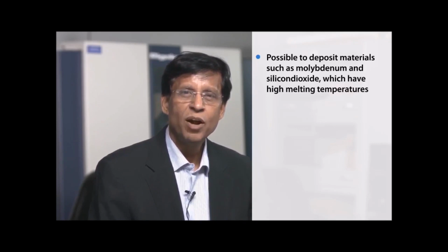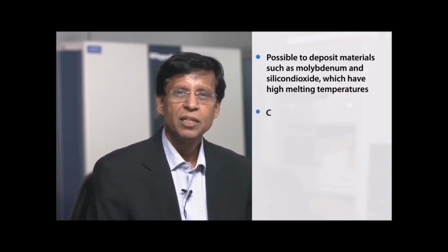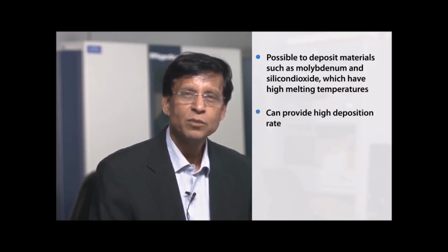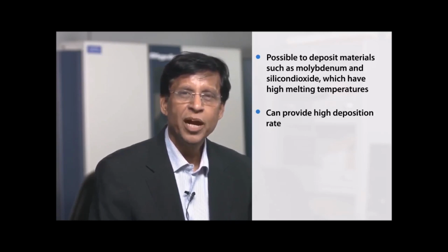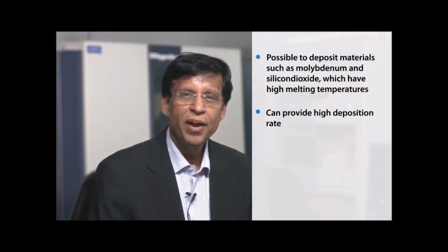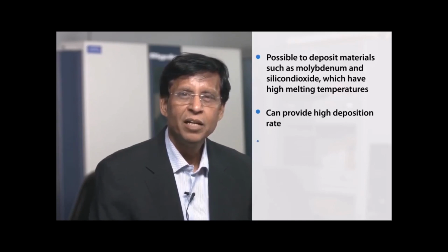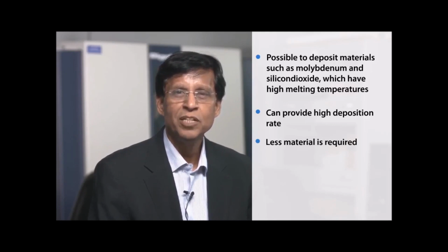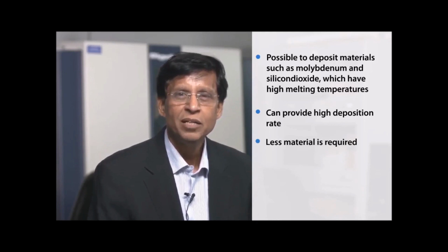The other advantage of this technique is that it can provide a very high deposition rate. As I described, it's possible to increase the electron energy, and then it's possible to deposit the materials with a high deposition rate. And since the energy is given in a controlled way directly to the material itself, this reduces the cost of material wastage, because the hearth is not heated. The temperature of the hearth is kept at room temperature or a lower temperature, whereas the material temperature can be increased to a very high temperature for melting the material.